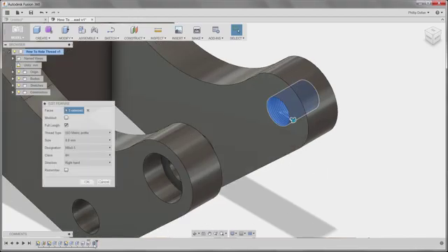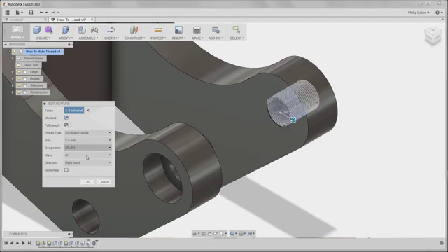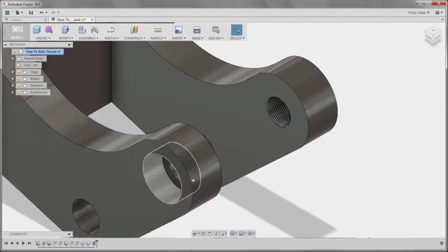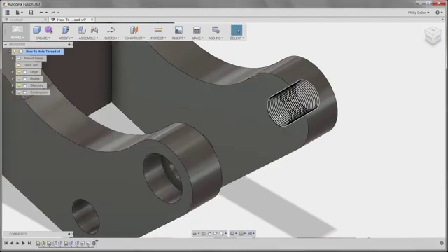I'm going to be 3D printing this model, so I right-clicked on my timeline, checked off Modeled, then clicked OK. Now that's actually a threaded hole, so when I 3D print this, it'll be correct.